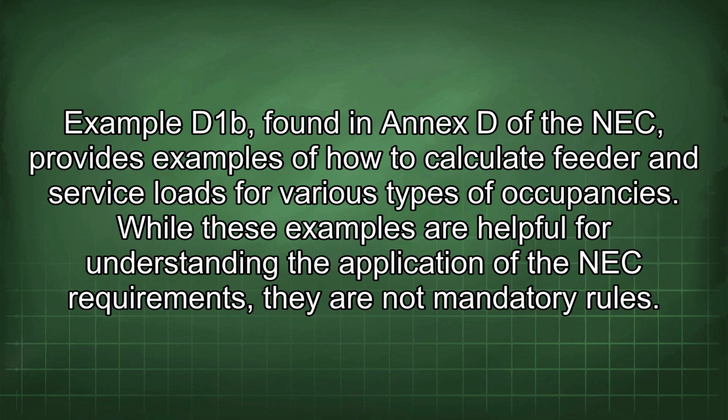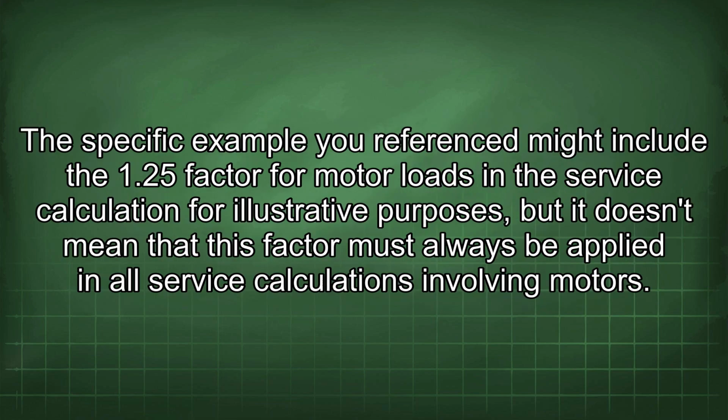The examples found in Annex D of the NEC show how to calculate feeder and service loads for various types of occupancies. While these examples are helpful for understanding the application of the NEC requirements, they are not mandatory rules. The specific example you referenced might include the 1.25 factor for motor loads in the service calculation for illustrative purposes, but it doesn't mean that this factor must always be applied in all service calculations involving motors.